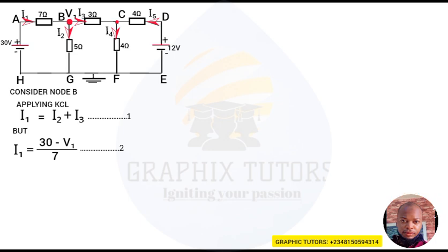Similarly, to get I2, I2 is in between V1 and the reference point, which is the earth here, right? So at that point, anything at this baseline is taken to be what? 0. Is that okay now? So it will be the voltage from where the current is coming from. The current is coming from V1, right? That is at node B. It's coming from V1. To where the voltage is going to, there's nothing there. So we'll say 0, right?